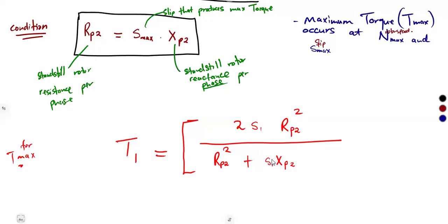We are finding the rotor reactance. This is our rotor value, all right? But we are supposed to square the whole of this part. So that's squared. This whole part is affected by the maximum slip, so you're supposed to multiply this by the maximum slip. Just like that. So that is what we are going to have as our formula.